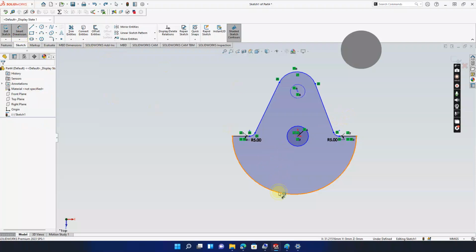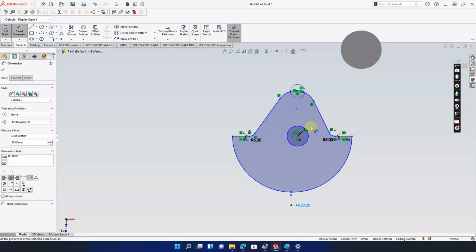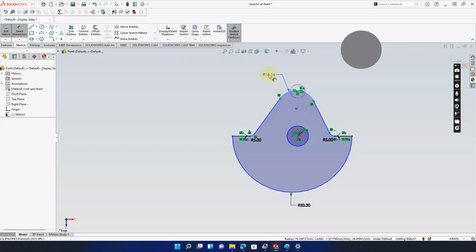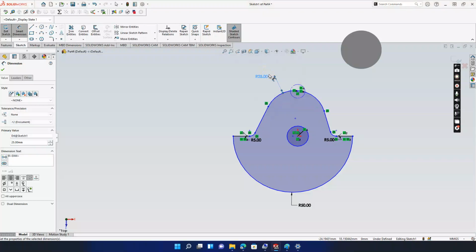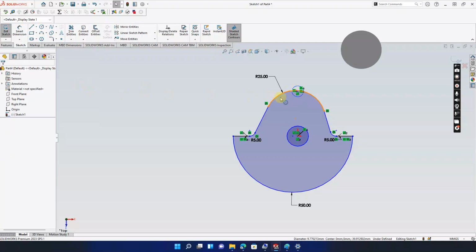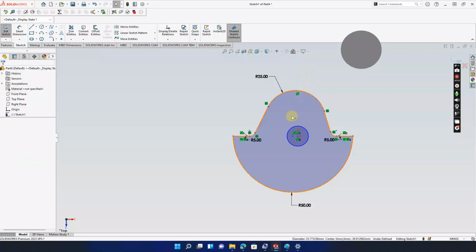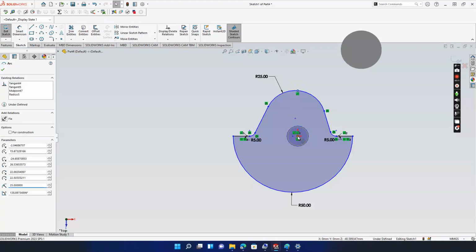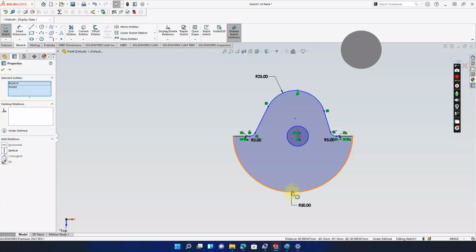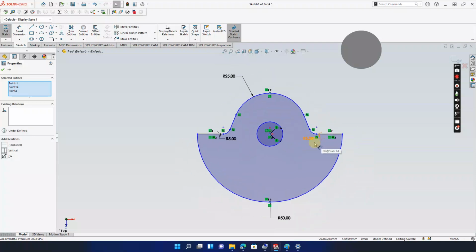Also, smart dimension: this has a smart dimension of 50, and this has a smart dimension of 25. So this, you can maybe just pull this, okay? Or let's just delete this, and now that even makes things easier for us. The center of this and the center of this and the center of this, make relationship vertical. Good, so everything's aligned. Our values align. I think that makes sense.